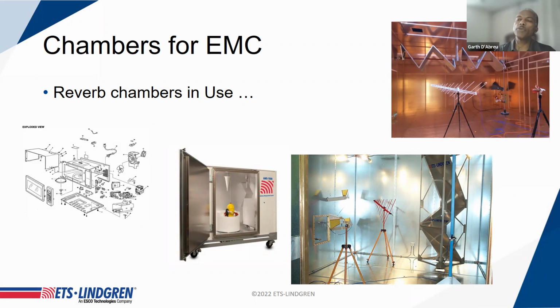In the EMC community, we've grown accustomed to much higher levels of uncertainty. I talked about the NSA test with a plus or minus 4 dB field normalized site attenuation limit for acceptability in the standard. I mean, that's an 8 dB spread.